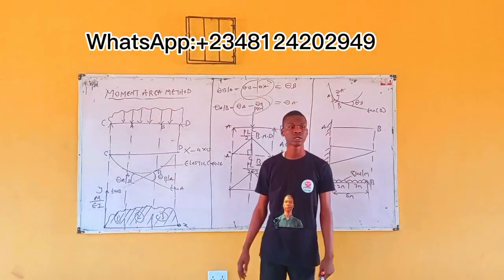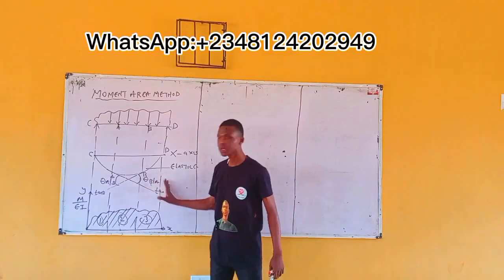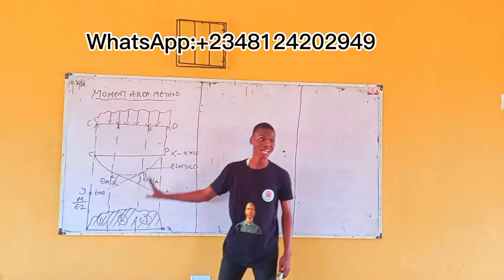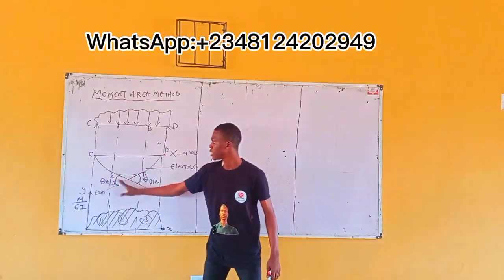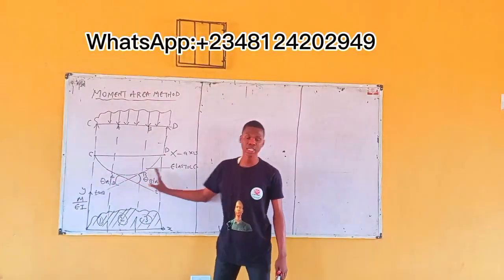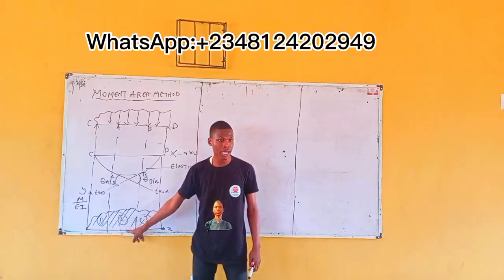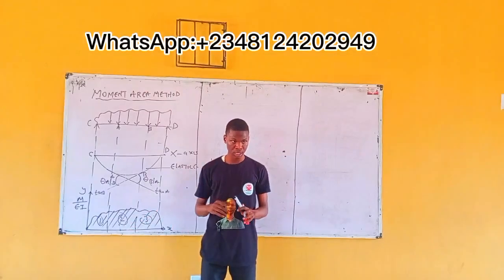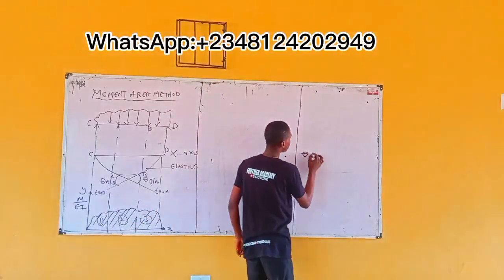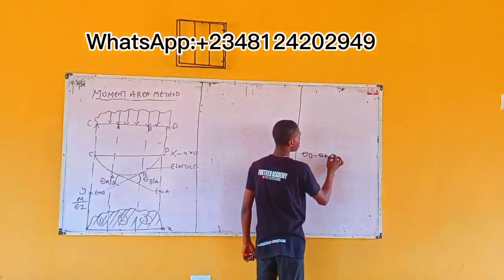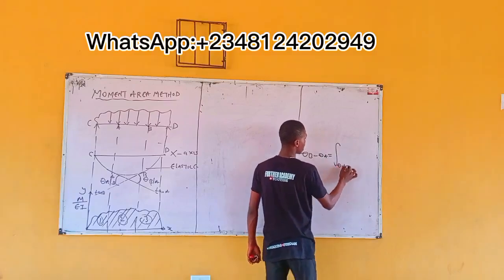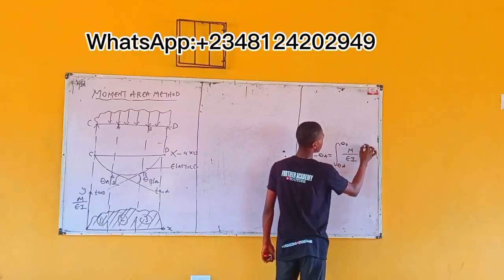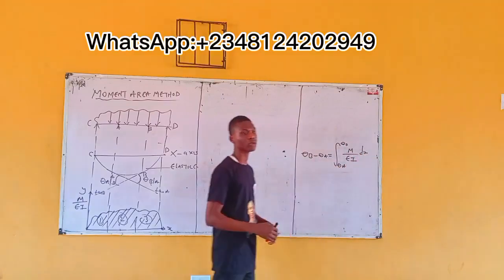That's theorem 1. Generally, what it means is that this is the relationship between the points on your elastic curve. I already know that the slope between them is equal to the area under the M by EI diagram, right? Now, let's see the mathematical formula for it. This is the formula: theta B minus theta A is equal to the integral from A to B of M by EI dx. Are you with me?